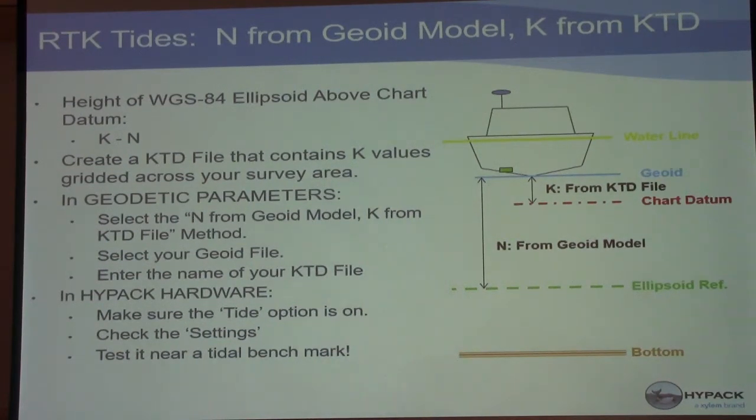Yeah, that's a tough one, because mathematics-wise, we know it all works out properly. Usually, we'll get data sent to us, and you go through all the math, and everything comes out to what it's supposed to be. Whether it's matching the gauge, is the gauge set up properly too? So there's a lot of variables there. Fortunately, in HYPACK, you can do the recalculate if you realize maybe there is a shift that I need to enter, and I can run the recalculate RTK if I have to in that process. So it doesn't hurt to collect all the data anyway, and you can always replace that with your tide gauge information after the fact too.